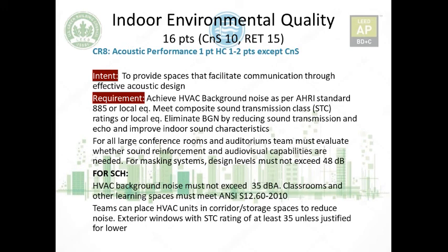Sound masking helps eliminate awareness of pre-existing sounds in a given area and can make occupants more comfortable and productive. So this is trying to cover another sound you produce, a masking sound. In that case, if you are producing a sound, a white noise, under the masking system, the design levels must not exceed 48 decibels. As I said, it's a bit more complicated, but I'm trying to simplify as much as I can.